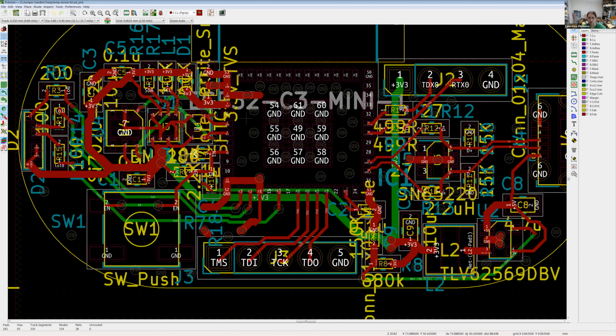So like this section over here, all these 3 sensors had to be really close to each other because they all shared the same I/O lines, and they also shared the same power lines. And then it just naturally fell in place that this is the JTAG controller, JTAG interface. It made sense to put it here because it lined up perfectly with the I/O lines here.